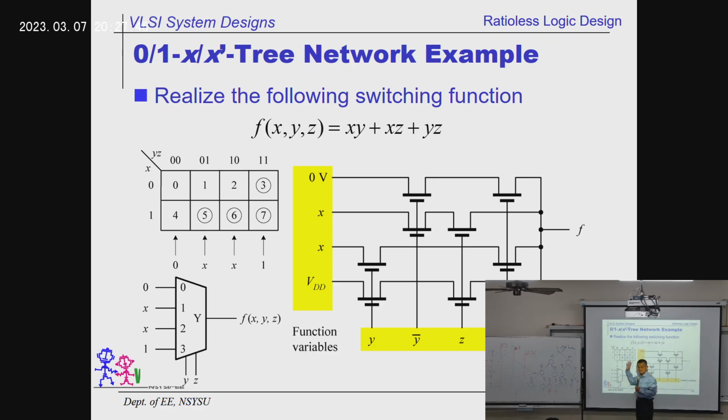So this is not K map. Please keep this in mind. This is residue map. Okay, don't mess up. And when you see those min terms, you make a circle. Okay, and then, as I say, all the residues are written over here so that you don't mess up. So if there is no circle, the output is 0. We have 2 circles here, we got 1. And these 2 columns, they are mapped to 0 and 1, so the input got to be X.